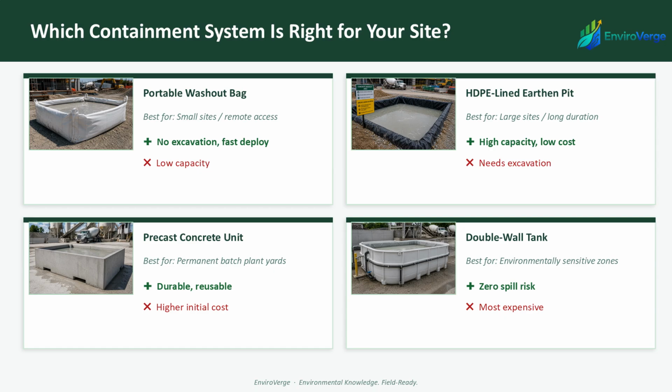HDPE-lined earthen pits are the standard specification for large construction projects with sustained concrete operations, essentially unlimited custom sizing, low material and labor cost, and straightforward decommissioning at project closeout. The requirement is space and early planning, not something you add after concrete operations have started.